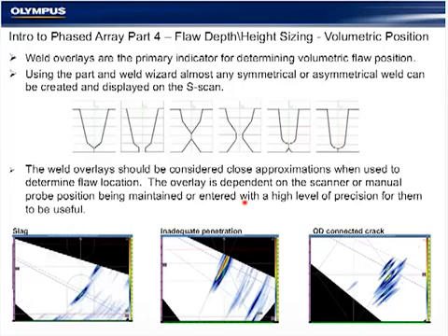And again, I had listed this as fourth, but in conventional manual UT, it's generally our number one indicator to tell us what a particular flaw is, where it exists in the weld. In this example, the weld overlay wizard allows the data to be superimposed on the position of the weld, making this a much easier function.